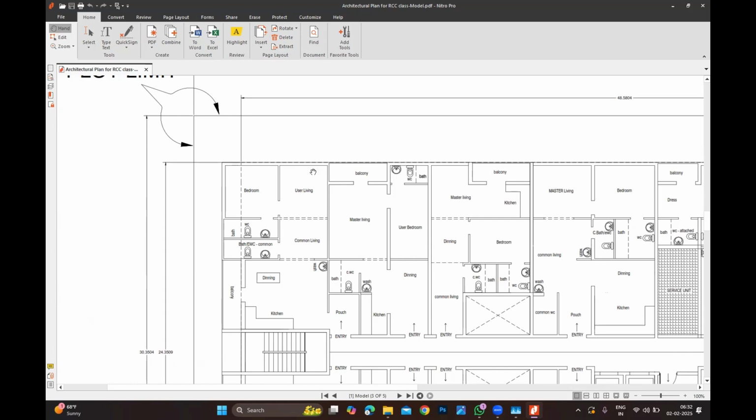If the client is looking for hollow block load, you can insist they go for AAC, aerated block load. The other panel which I showed, Fortis panel. Remember, this is a lightweight panel which they started in Dubai. If you look, most of the towers were using only Fortis panel. You don't need any kind of plastering.